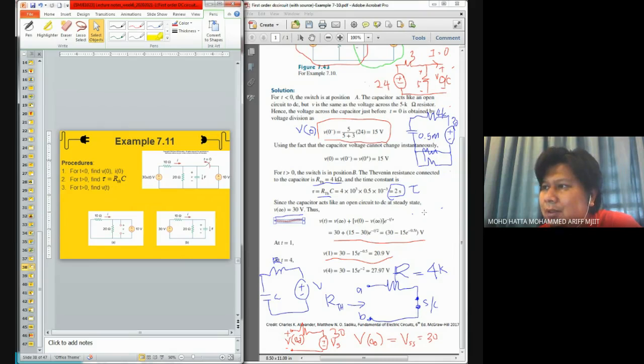For this example, the source is voltage, so that's why we put it as short circuit. And if you have a current source, you should consider it as open circuit at this part. Again, for VTH, please redraw the circuit and imagine the circuit being kept for a long time, or when considering that t towards infinity, what would happen to the capacitor?